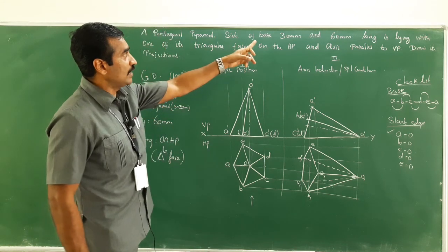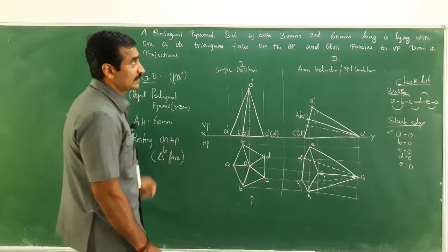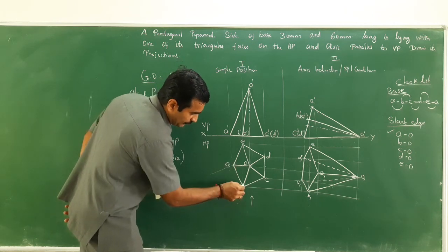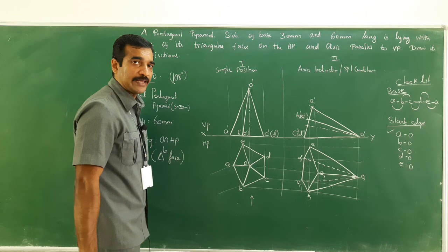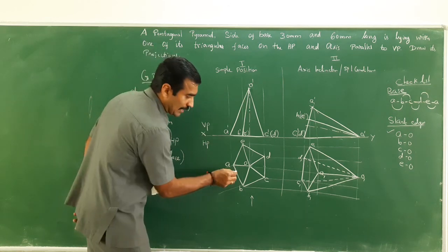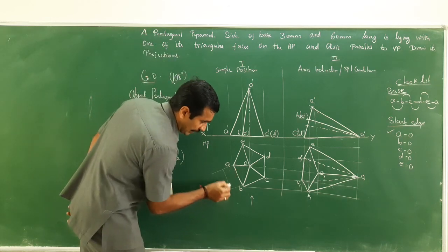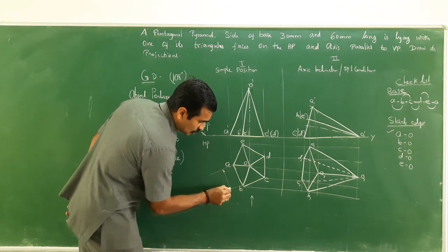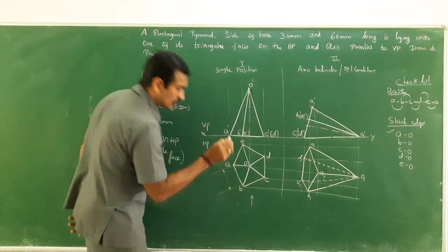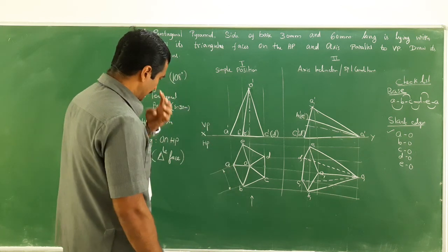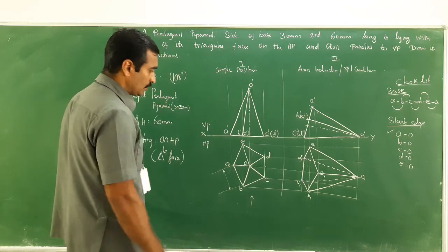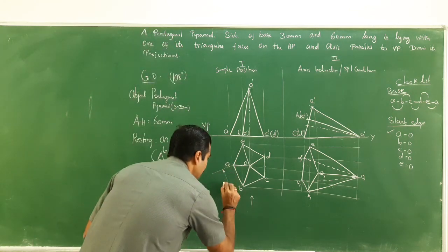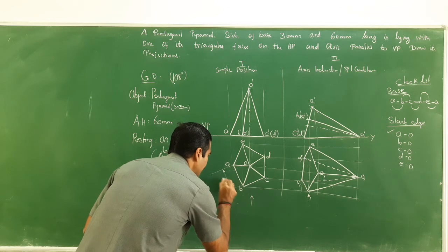So first, the side of the pentagon is 30 mm. So draw a perpendicular line to the side, that is the extension line. Now draw a line which is parallel to this side, that is the dimensioning line. So now fill the arrow. The arrow head should be 3:1 or 1:3, right? The width is 1 and the length is 3. So over this you will have to write it, right? 30 mm.